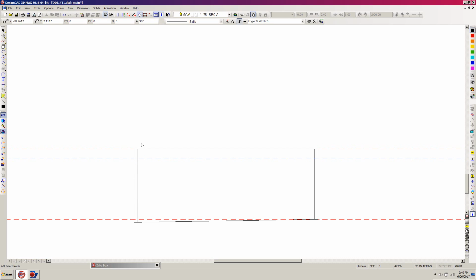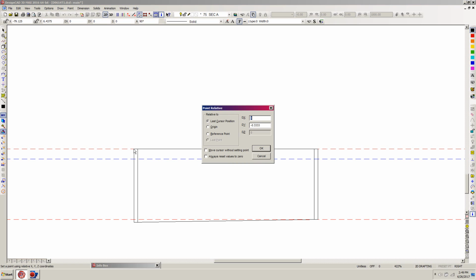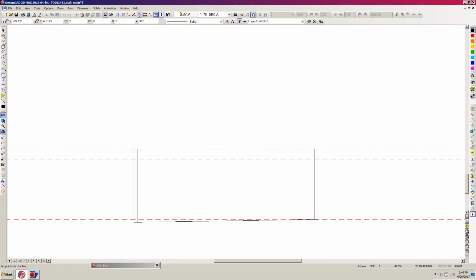So I'm going to hit V up here at the top, and gravity move, that's comma, and hit my point relative apostrophe again. I don't want to move the x-axis at all, so that's 0, and I'll hit tab and go minus 1.5 inches for my plate. Then I'll hit H so that I'm in orthogonal mode. That gives me a nice straight line, and I just right-click to this point there, and click my scroll button on my mouse, and there's my first plate.